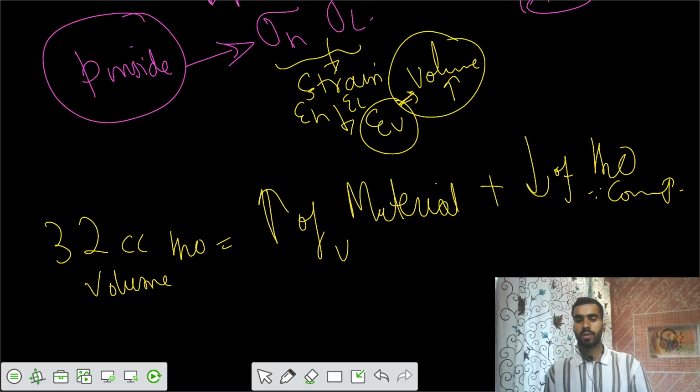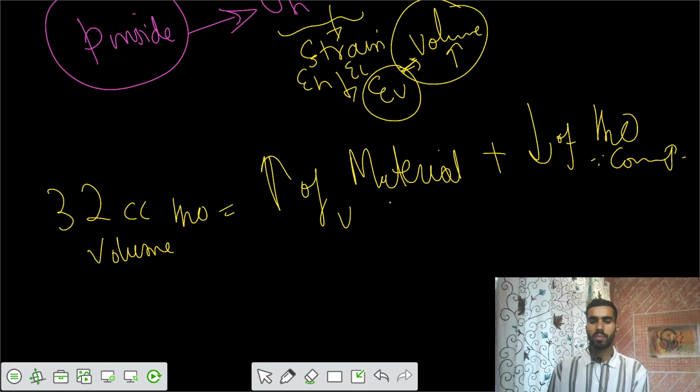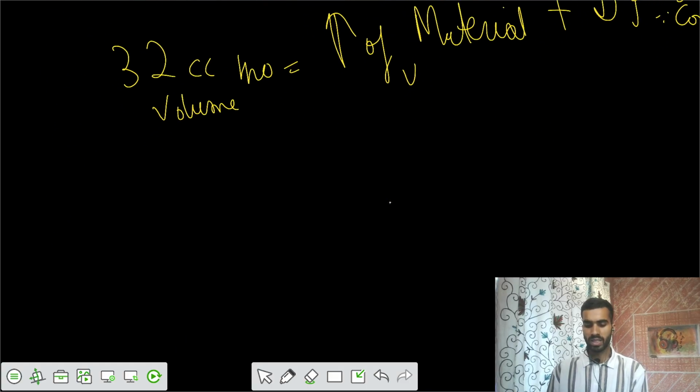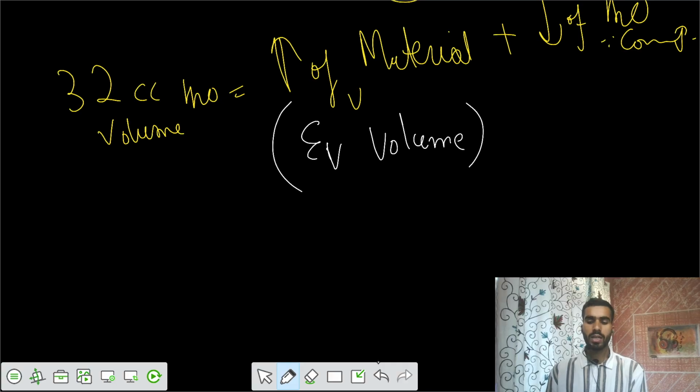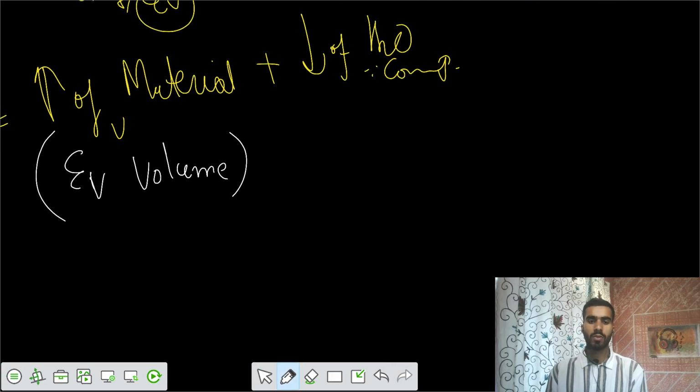So if I calculate, what is the volume increase of material? I need to calculate that. That is volumetric strain times the total volume, so that is the change of volume of material, plus what is the decrease of volume of water?